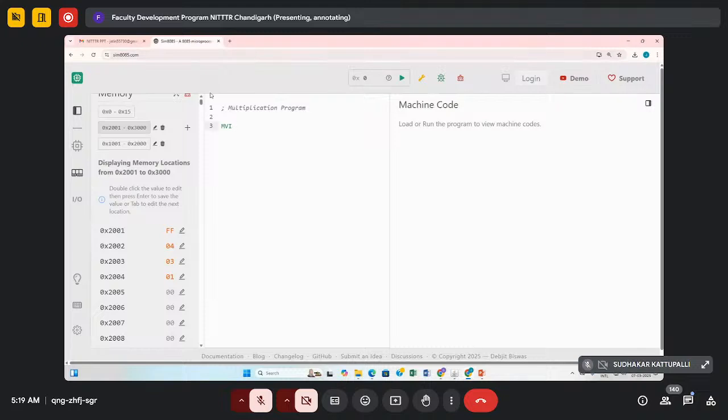Okay. So what I'm doing is initially, as in the last case there can be a carry, so I'm initializing D for carry. There can be two methods of doing it. Now let us do indirect addressing in this case. In indirect addressing, we will store the memory location in some register pair and we'll point to that memory location. We have already done register direct and immediate, now we'll do indirect addressing.